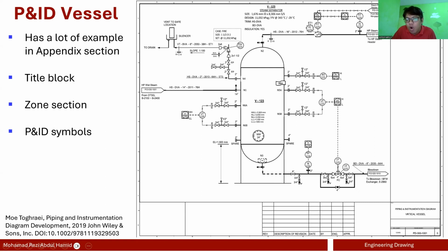And then since there's liquid on the line, I can open this drain valve to remove all of the maybe corrosive or very nasty liquid from the pipeline before I take out this control valve for maintenance. So that's the use of this one. And then this one, I also have a drain valve here, but it's not really connected to this control valve. This one is basically for you to drain the entire line in case you want to do a shutdown or something like that. So yeah, and then you can install a new one, and then you can close this one, you can open, and then it will resume as usual.